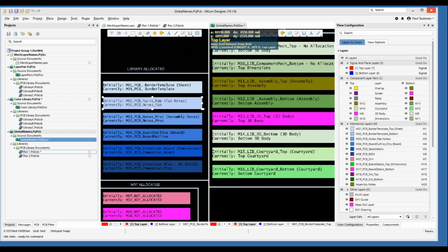They're definitely worth playing with and trying so you get a better feel for them. But they do a really good job of fixing these issues where you bring in the library from one thing and you've got something from another and you're trying to bring them in. Though I'll be perfectly honest with you, I think from the get-go you want to make sure these mechanical layers are right before you bring them into your PCB doc. But this at least can remedy some of those issues.